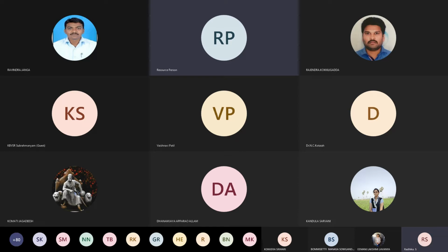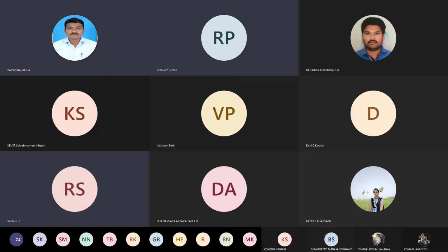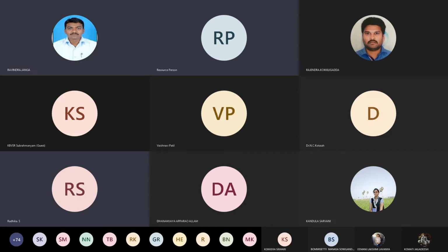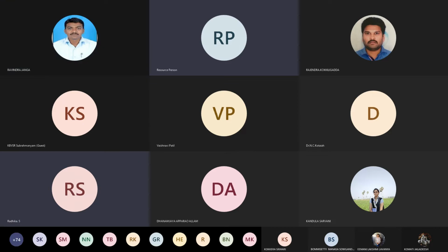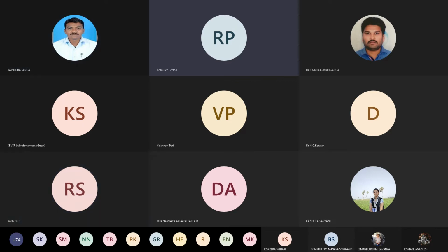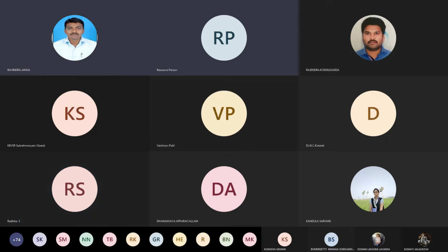Sir, I have a doubt. When you are selecting the switching frequency, you said it is based on the solid state switch. You selected it to be 100 kilohertz for the boost converter also. How did you select it? Based upon the rating of the components available in the market, we need to select it.